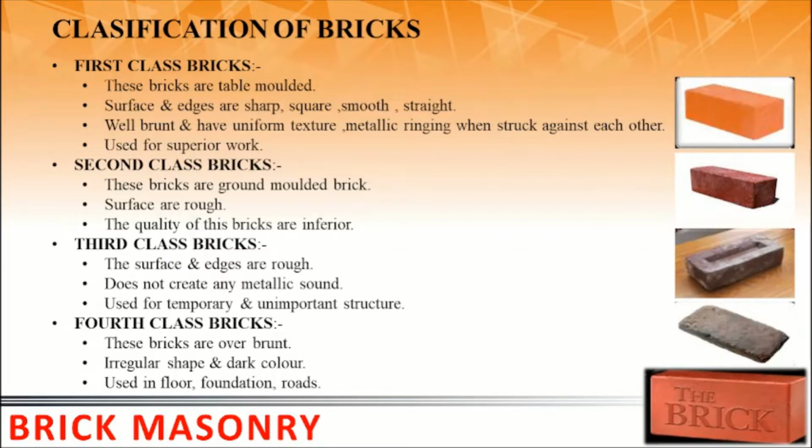Now the fourth class bricks. These are bricks which are overburnt. They are of irregular shape and dark color. These can be used in floors, foundations and roads, but they can't be used for the superstructure.